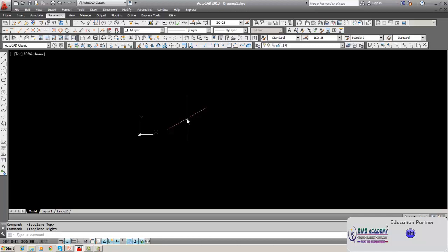So this is called the right face, this orientation is called the left face, and this is called the top face. That means there are only three faces we can draw in the isometric view, and other faces can be drawn, but they will all be shown as hidden. As far as possible, avoid drawing hidden lines because they give more confusion. Okay, now we'll start working.